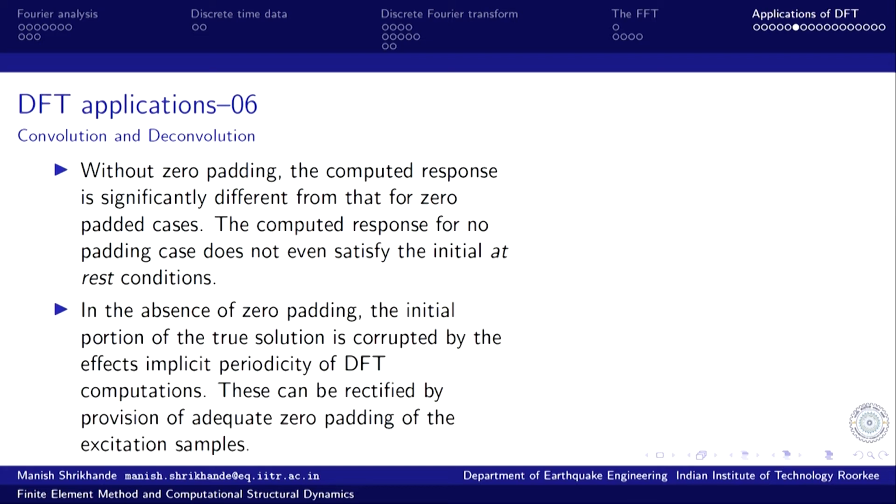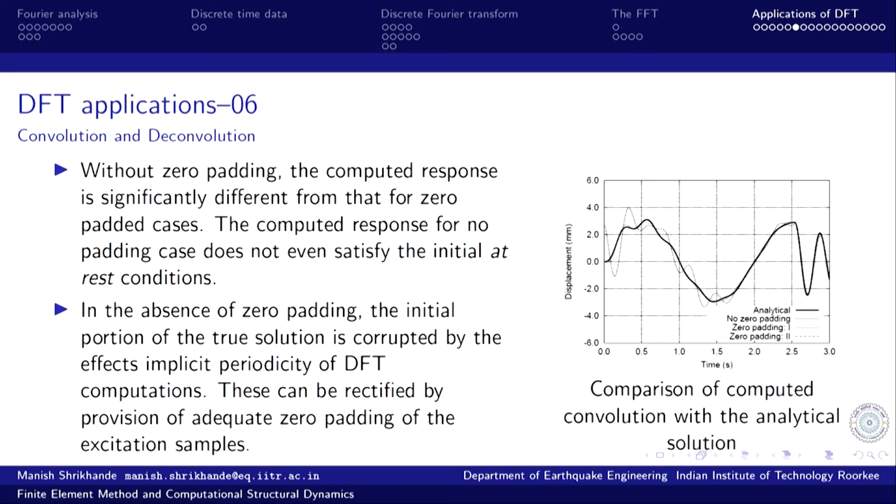In the absence of 0 padding, the initial portion of the solution is corrupted by the implicit periodicity effects of DFT computations. These can be rectified by the provision of adequate 0 padding of the excitation samples. So, we compare these 3 cases after we remove the 0 padding, so that we can plot all of them on the same common time axis.